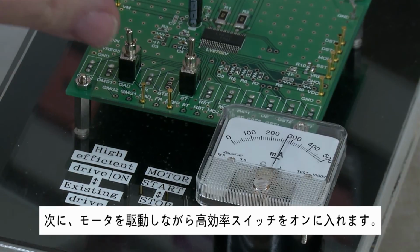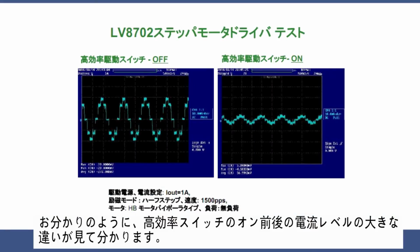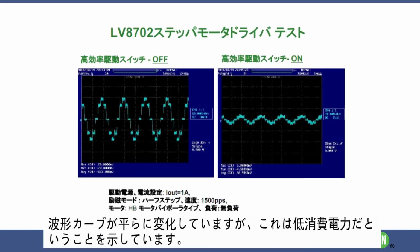Next, while keeping the motor driving, we turn on the high efficiency switch. As you notice, both motor noise and vibration are decreased as soon as this product feature is activated. You can also see the significant difference in motor current level before and after the high efficiency switch is turned on. The waveform becomes more flat, which indicates lower power consumption.